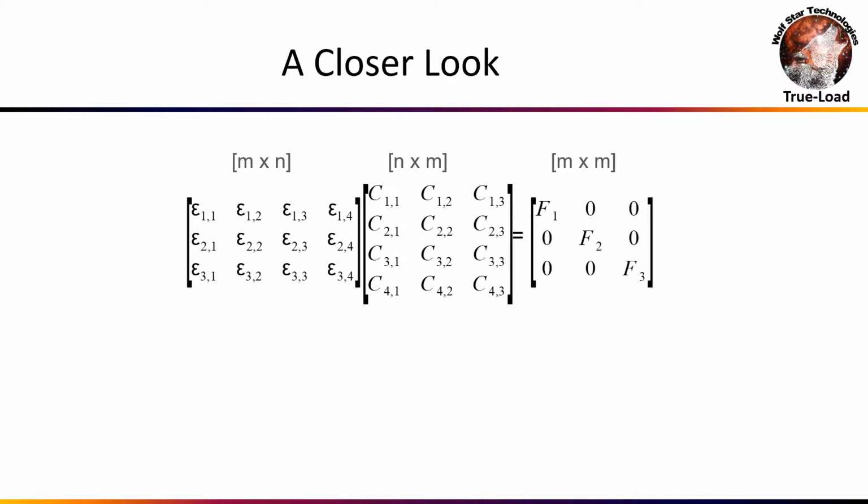Let's say we had a cover on a structure and that cover was bolted down on its 4 corners. We solved the cover for its mode shapes. And where it's bolted down at those 4 corners, we put unit displacements X, Y, and Z on the 4 bolt locations. And we laid strain gauges based on all of that.